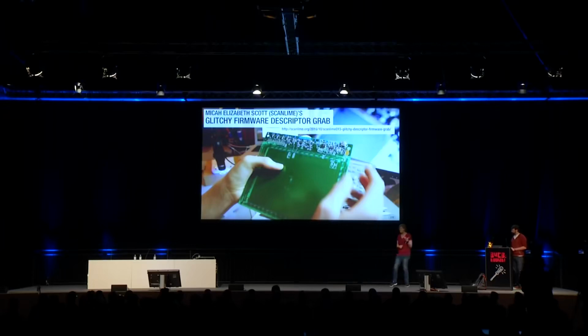And that functionally looks a lot like an RFID chip, which also does a kind of load modulation. Whereas the pen was receiving power and then loading the power lines in order to communicate where it was on a grid and how hard the nib was being pressed, an RFID takes power and then just transmits back via that load modulation a simple fixed ID. So she had the idea that those are basically the same pieces of hardware, just the pen in this case was a little bit more complex.